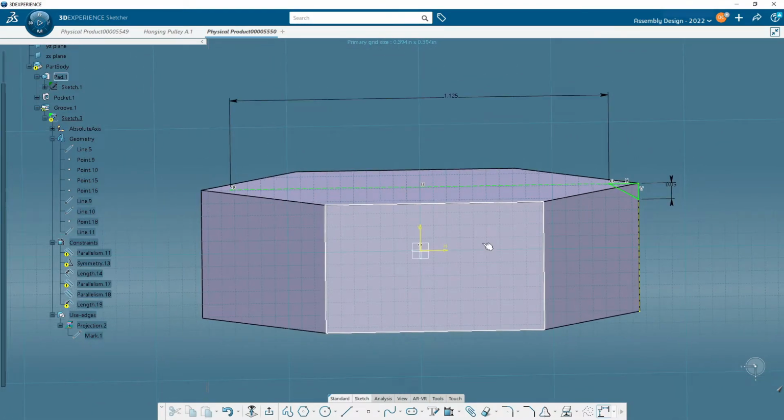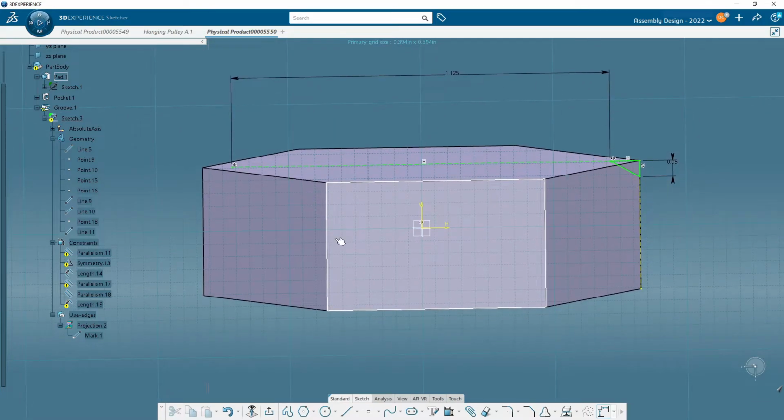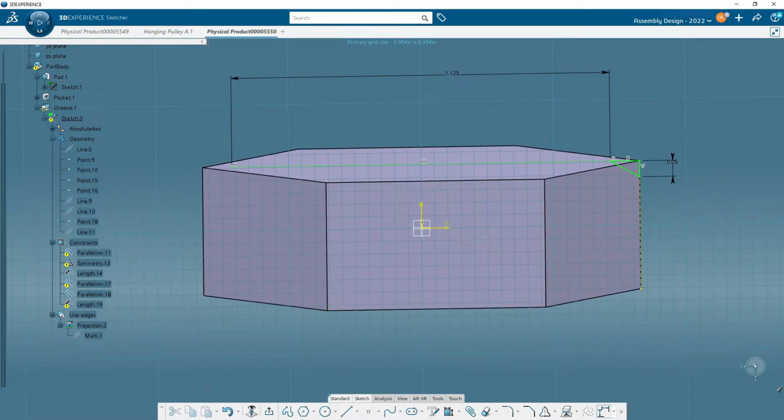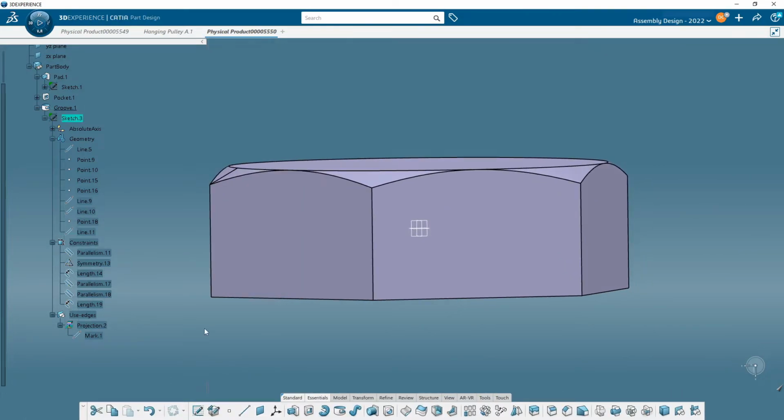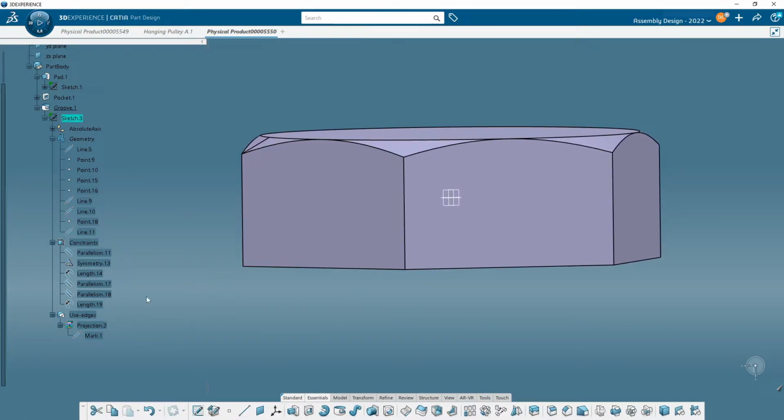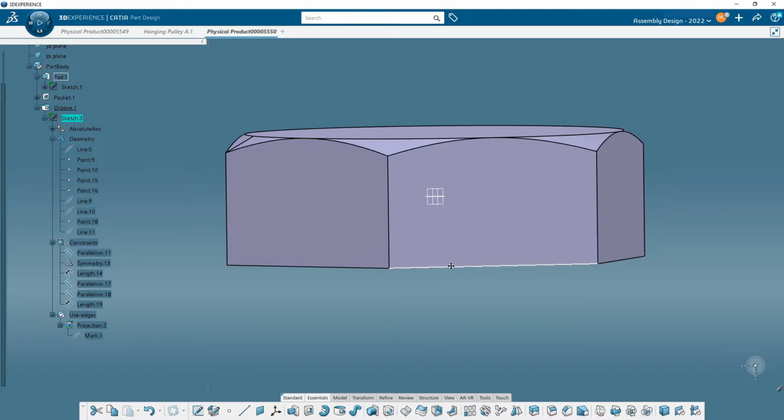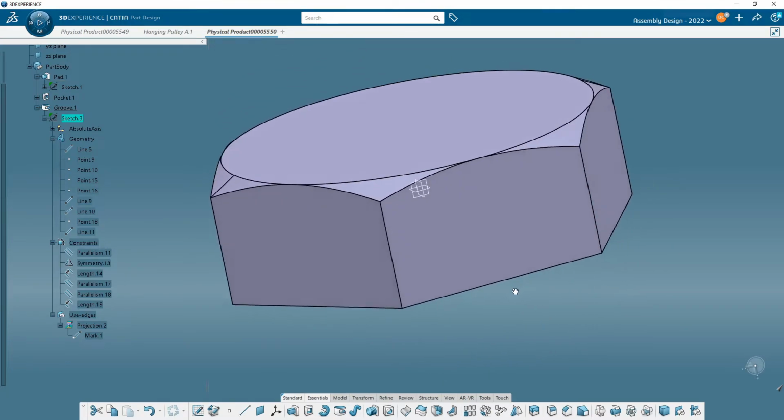Okay. Now, let's continue on with some of the rest of this. If I exit out of the sketch, everything updates. Now we're okay. If you had more problems, if some of those problems that were yellow in the sketch, the exclamation mark, if you exited out and they remained an issue, you would get a warning again pop up here, and then you'd have to go back into the sketch and continue working on it, okay?